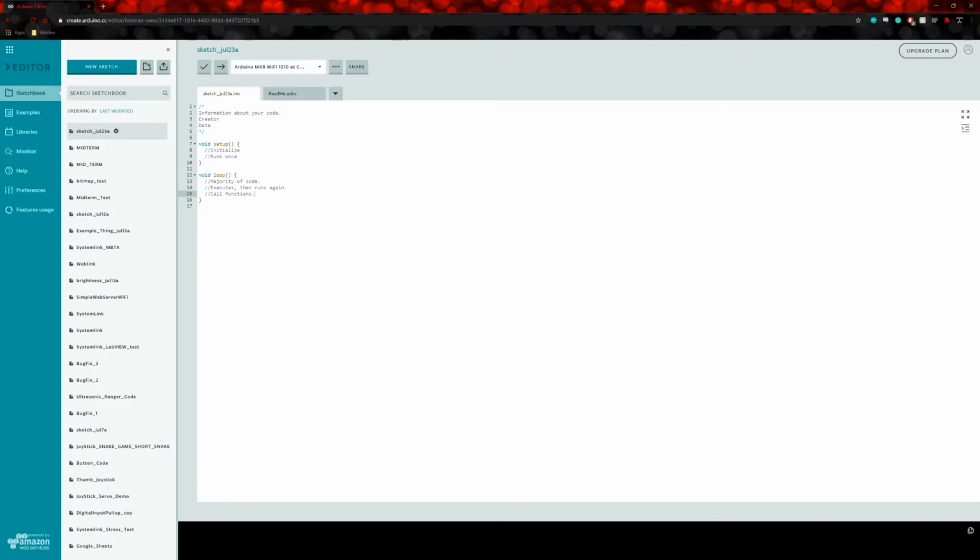The first basic command you should know is Serial.begin. Serial.begin accepts a long type input. The most common value you will see is 9600. This command opens the serial port and sets the baud rate, which allows you to use the Serial.print and Serial.println commands, which are Arduino's print commands.